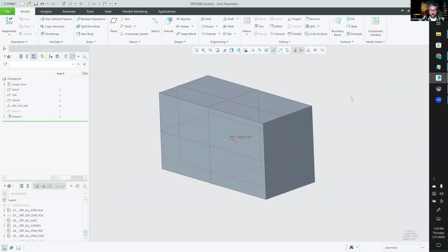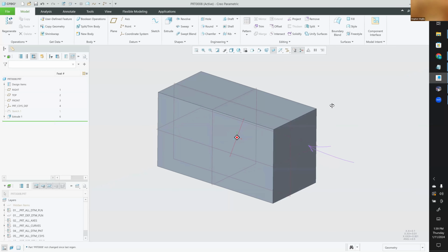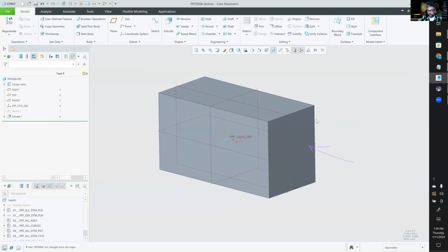Okay, can you see my screen? Yes. Okay, so just to reiterate the obvious, right? This orange sketch is the rectangle that I extruded, the sketch plane. Okay. And this might sound irritating, but this was new in Creo too. So if I hover over that edge and don't click on it, just right click on it, it fetches all four of the edges that went up.